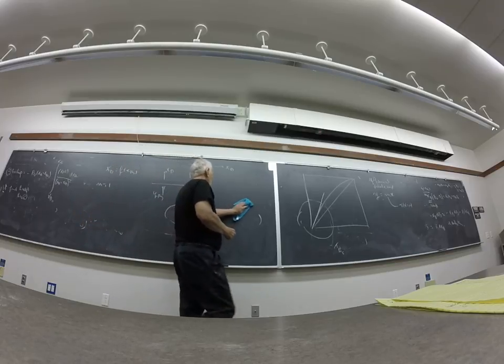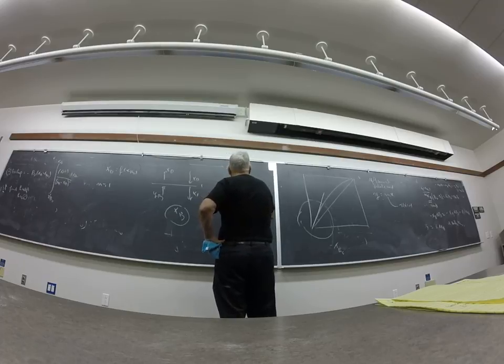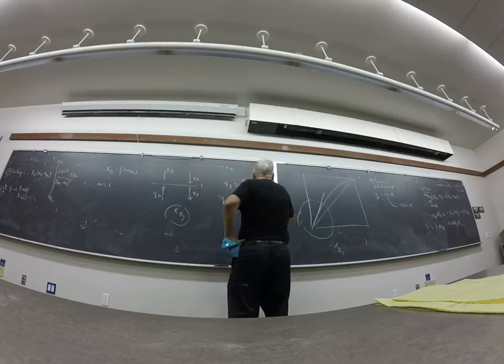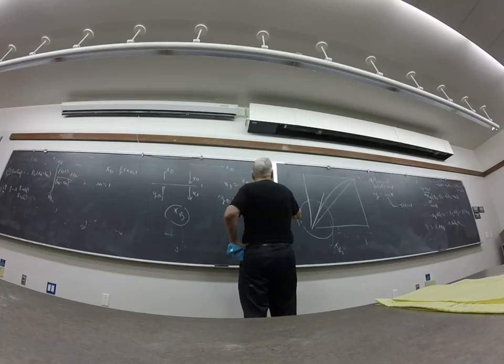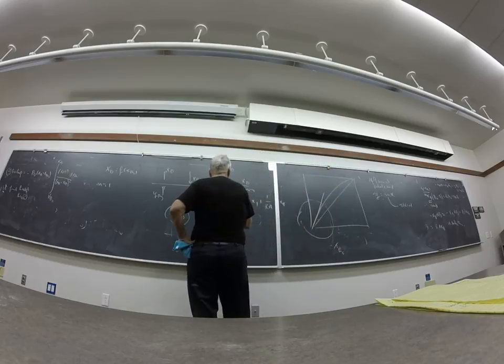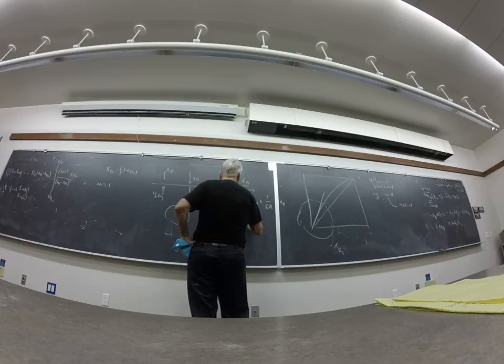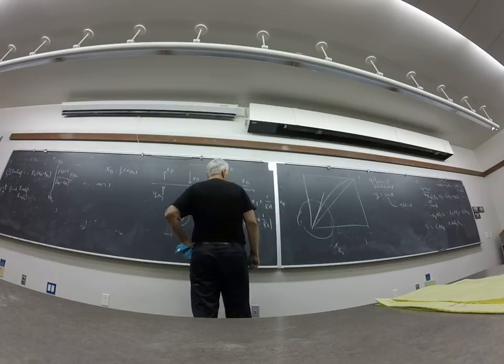And I begin by saying something like this: x1 equals xd divided by m. I want yb. yb is equal to r over r plus 1 x1 plus 1 over r plus 1 xd. I put x1 in there. I get r over r plus 1 times 1 over m plus 1 over r plus 1 xd.